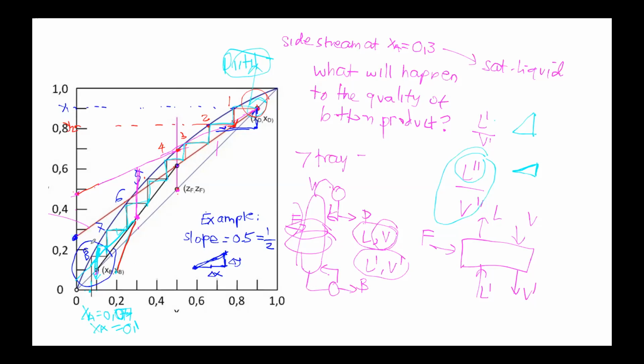If you think about the fractionation column of crude oil, first you want the LPG, for example. Then there is a side stream, a composition in the distillation column similar to gasoline. I want that because we need C6 to C9, the naphtha, for example.